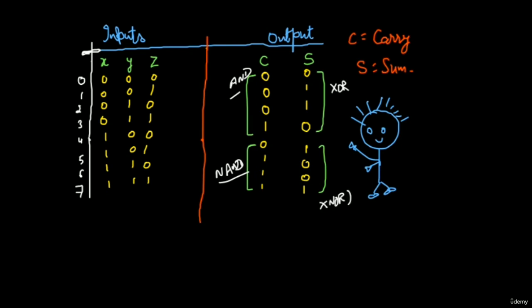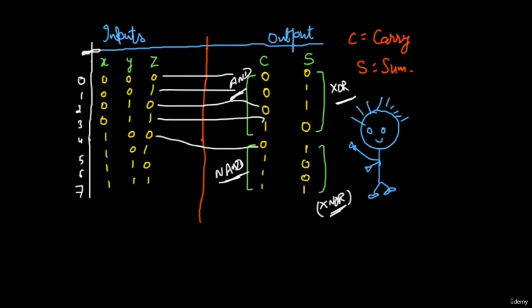Now you do not need to remember all the zeros in one sequence. You can just remember, write down AND and then NAND for the carry, and for the sum you have to write XOR and then XNOR. That's the whole idea of it. I hope you have understood all these things, and obviously this signifies these terms. I'm trying to present it, though it has gone a little up and down because of my writing style, but I hope you have understood all the things that you need to know and learn, my dear friend.